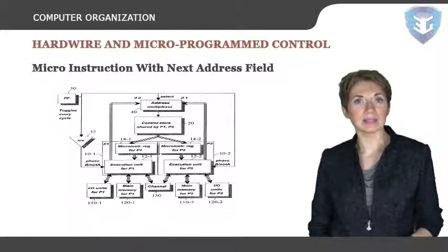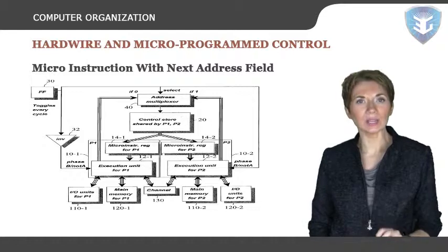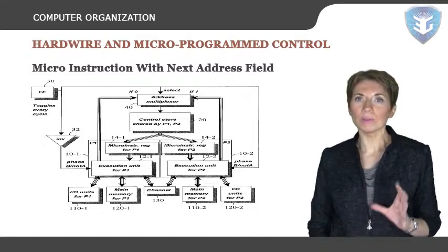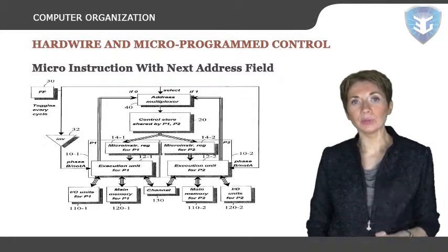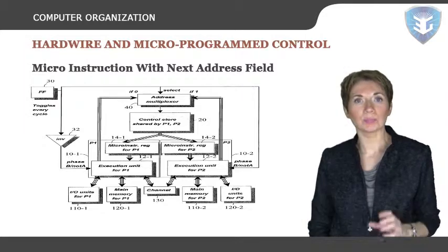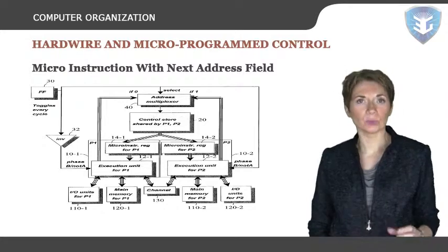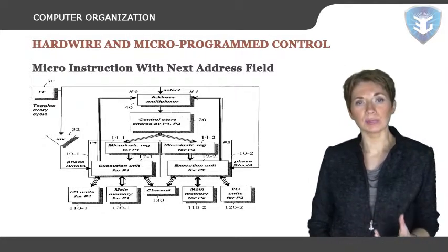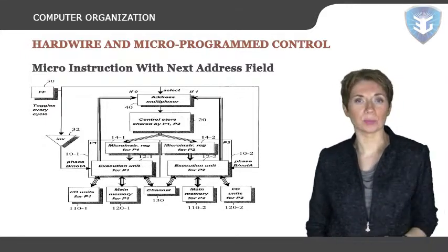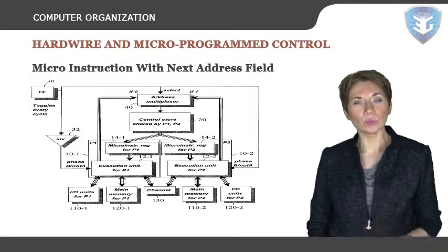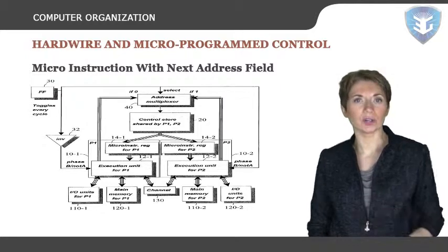Its severity can be assessed as follows: in a typical computer, it is possible to design an adequate microprogram that governs most control functions with fewer than 4K microinstructions, employing perhaps 50 to 80 bits per microinstruction. This implies that an address field of 12 bits is required. Therefore, approximately 1/6 of the control store capacity must be devoted to addressing purposes. Even if more extensive microprograms are needed, the address field will become only slightly larger.